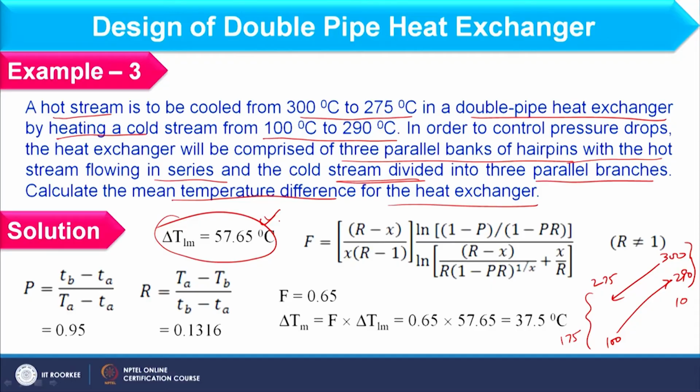P value, R value as well as the number of branches. So, P value is the thermal effectiveness of an exchanger and R is basically the division of heat capacities of two fluids. This we have already discussed in basic design parameters lectures, so you can refer to that.